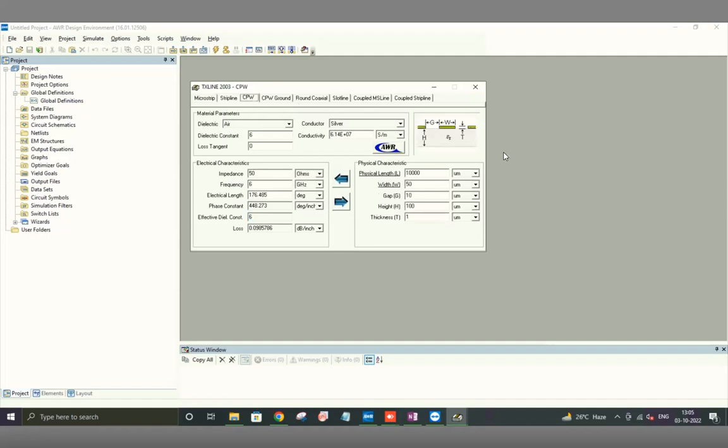So there is this thing called coplanar waveguide or CPW. So there's a dielectric slab of height h. In all of these planar transmission lines, the dielectric is basically what's called the substrate. That's the holder of the entire circuit. Then you have a center trace of width W, thickness T. Thickness here again plays a similar role like last time.